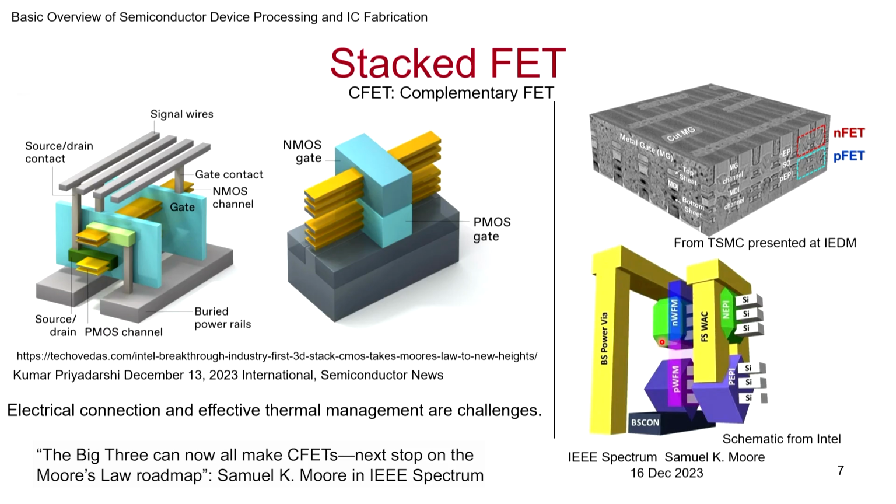The reason they are looking different is because they are of different orientations according to the need of the P MOSFET and N MOSFET. You want to maximize the performance of that. Typically, nowadays the mobilities of P MOSFET and N MOSFETs are coming close to each other. But that being said, if required, you can adjust the number of ribbons to be more or less on whichever has lower mobility. Typically, PMOS has lower mobility, so you could have more ribbons for the P MOSFET if you want to make the P MOSFET and N MOSFET balanced.